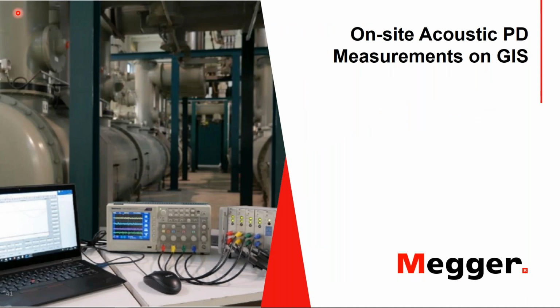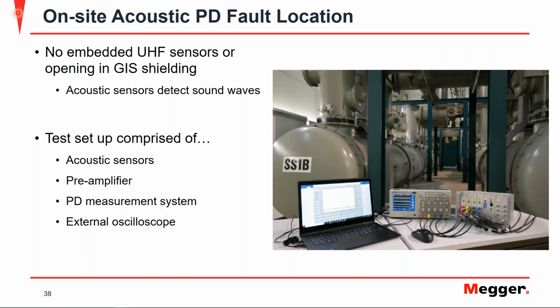So now that we've discussed the examples of UHF measurements, or the phase resolved partial discharge, let's take a look at on-site acoustic partial discharge measurements for GIS. Here we have an example where there are no embedded UHF sensors or no openings in the GIS shielding for external flange sensors. So therefore, acoustic sensors are used to detect the sound waves that are a result of the partial discharge taking place. And this test set is comprised of acoustic sensors, the preamplifiers we discussed previously, a PD measurement system, in this case the ICM system here, and then an external oscilloscope for just kind of redundancy and measurement and comparison.